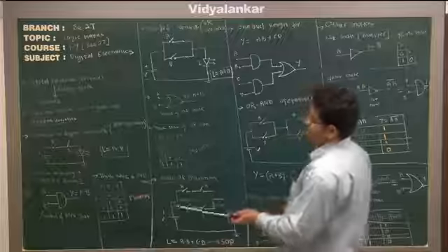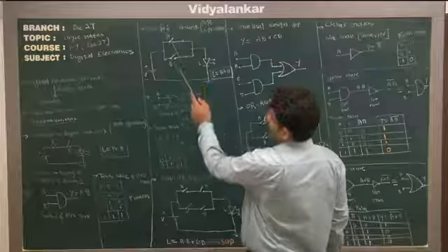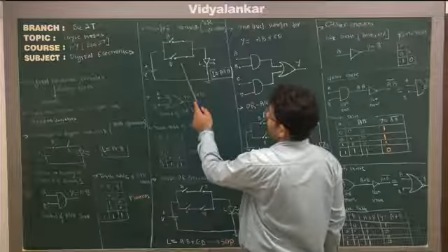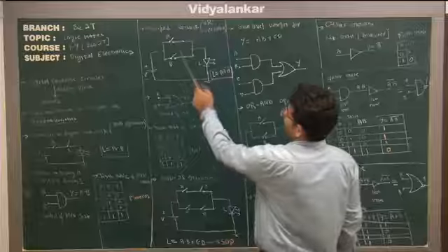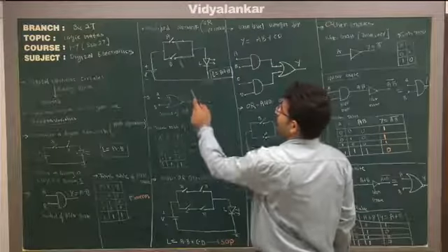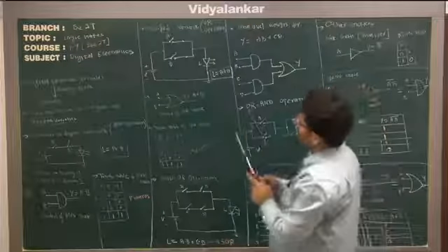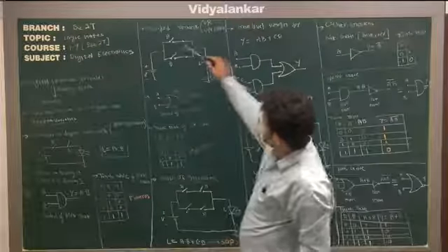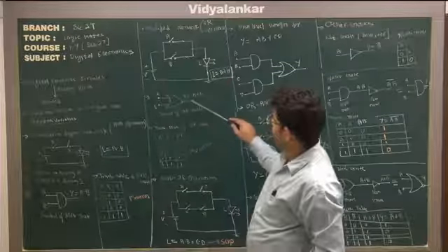If you compare this, in contrast to this circuit, if I connect switches A and B like this in parallel, then I'll get light from the LED whenever A or B is closed. So this is A plus B, or A or B. The digital circuit equivalent to this configuration is your OR gate.